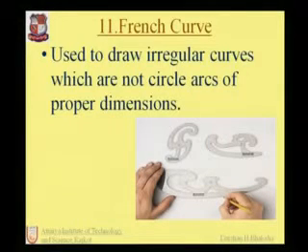The French curves come in many shapes. As per our applications, there are many sets of French curves. By combining and using the French curves, it is possible to draw different curvature shapes which have no proper dimensions. Mainly the French curves are used for drawing engineering curves. We will study the topic of engineering curves later on, in which the different curvatures should be drawn, and it is very useful to draw them with the help of the French curve.